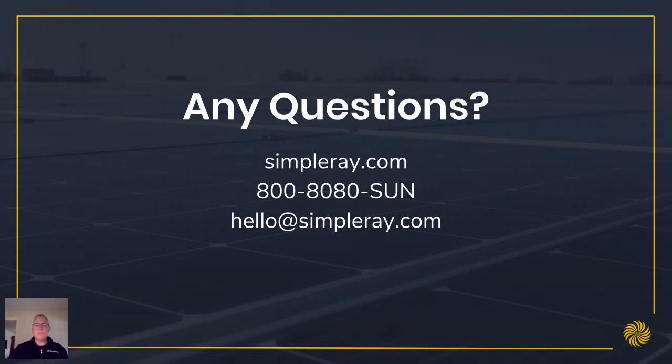How effective are panels after 40 years? That's also a good question. Generally speaking, for any panel that we're going to install, we're looking at a yearly production degradation of less than 1% per year, and really closer to 0.5%.